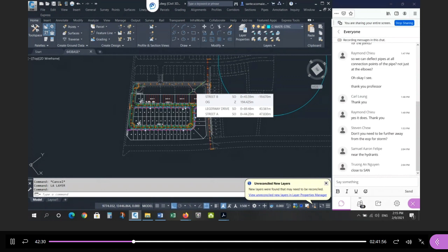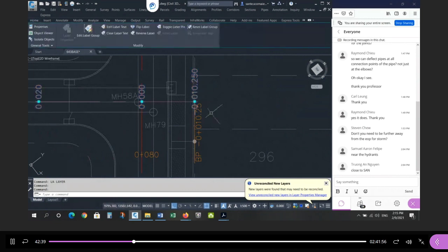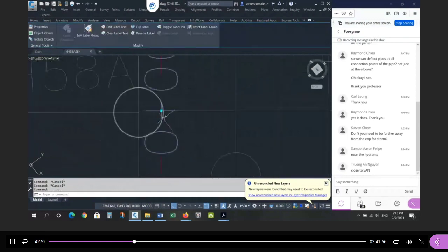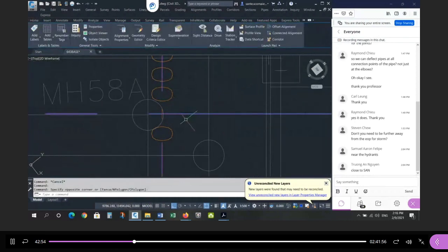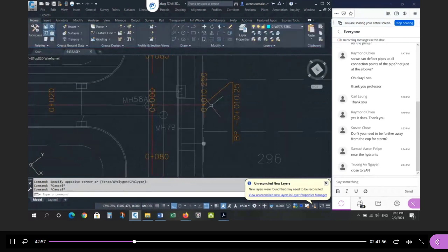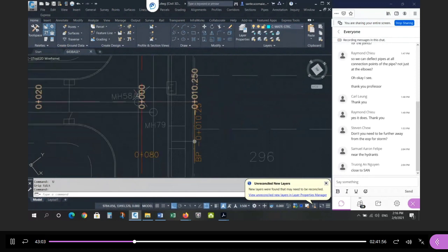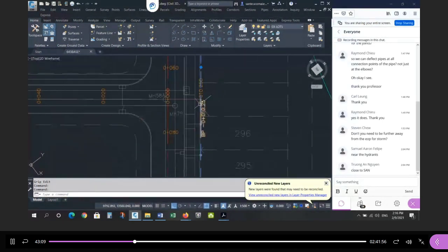So if you drew the geometry correctly and you put 0 in the right spot, right, where the intersection of the 2 center lines is, you should get a station value at the beginning of negative 10.250, right? That's the beginning, and that then proves that you put 0 in the right spot, the intersection of these 2 alignments. Okay? So the beginning station is negative 10 plus 250. The end, right, if that's in the right spot, which means you went all the way to the beginning of the alignment where the property line is on the opposite right of way for Ledger Way, that's the beginning, but 0 is here. So that's the station at the beginning.